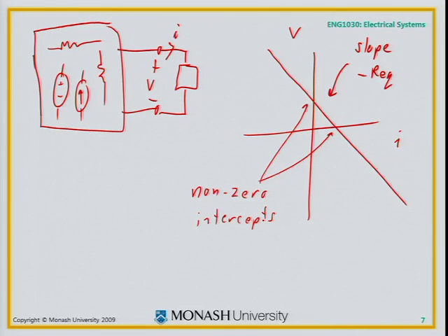Yeah, sorry? Does that include dependent sources as well? Yep. You can also put dependent voltage and current sources in there as well. Doesn't matter what I do. If I put a diode in there, no. Different story. All these linear elements that we've been talking about, that's all you're going to get. And so you could fully characterise it with 2 measurements.